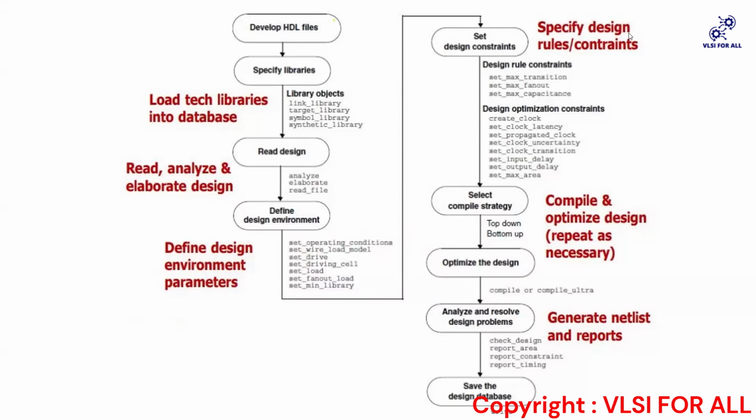No, no, no. Yeah, it's hardware description language. Okay, hardware description language. Yeah, most of you got it right. So this will be in .v or VHDL format, as I said earlier. After that, we need to specify libraries. While specifying the libraries, we need to load the libraries into the database.